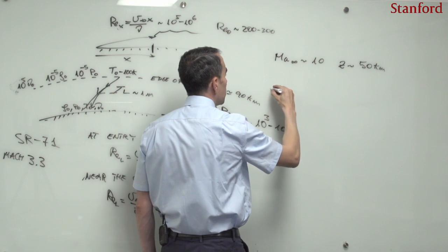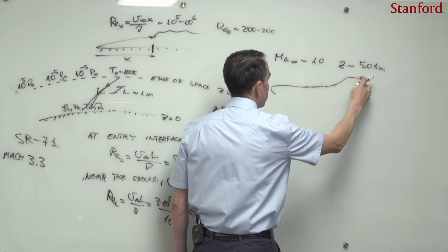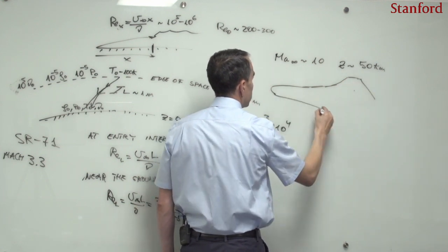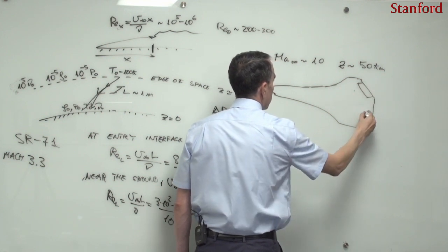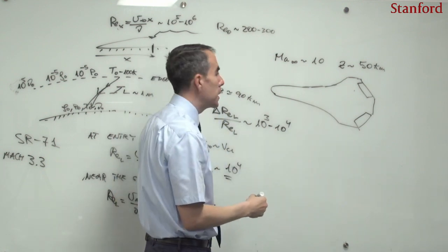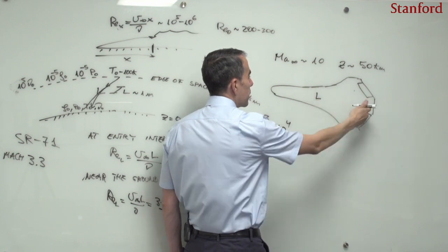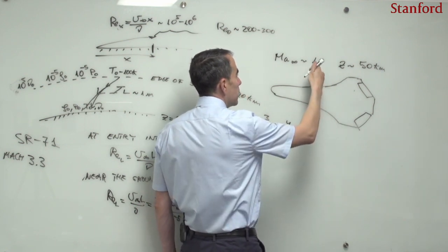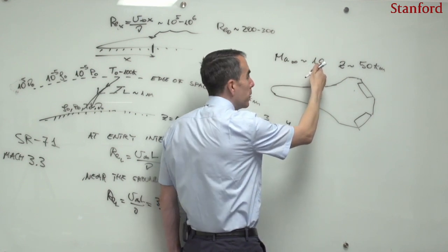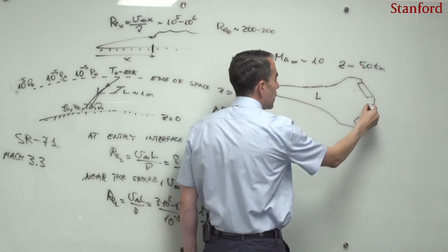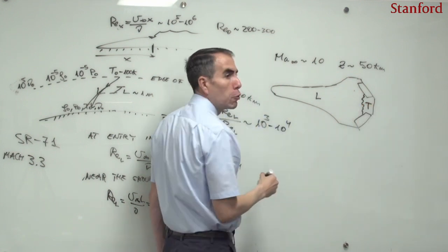And in the beginning of the transition period, what you have is that if this is the shuttle, here I'm seeing it from below, right? This is the underbelly. At high altitudes, the entire flow is laminar across this surface. But after approximately 1,000 seconds, the Mach number now has decreased to 10, and the altitude has decreased to 50 kilometers. Then one would start having here a transition front where the boundary layer will become turbulent downstream.